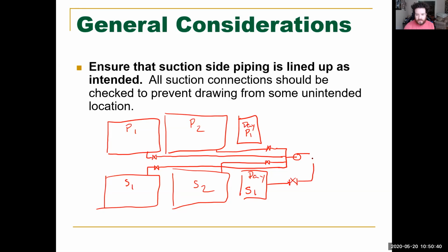All right, on your suction. If you want to suck from port 1, you do not want to have any of the other valves open. I know that sounds really obvious, but this is something that you should always be double checking, especially with fuel oil. All right? Because there is abilities to go like this and have this pipe right here, and this just goes to deck.